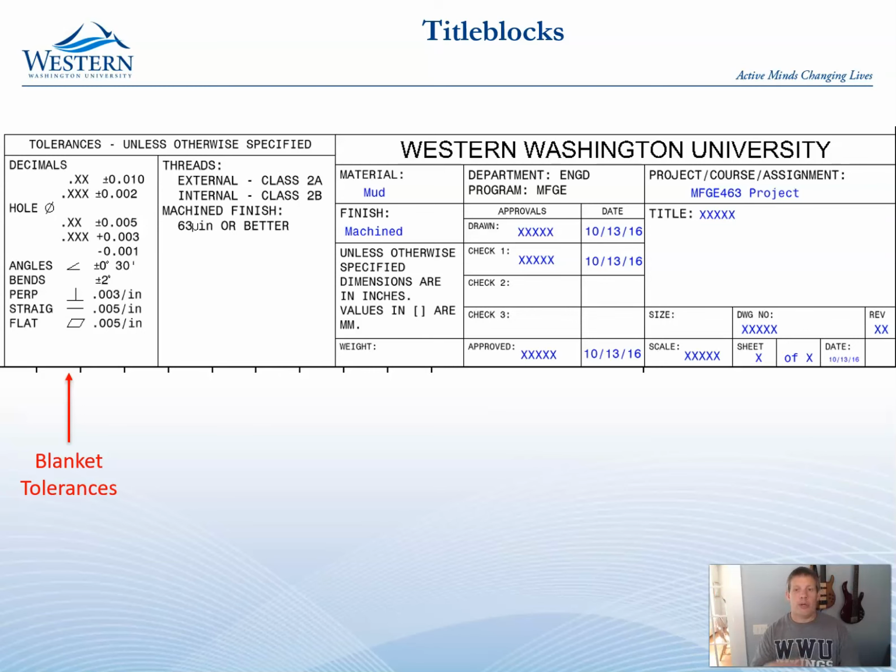But I don't ever want to see a drawing that has 4.3 inches and 2.1 inches, and then come down here to the table and see that there is not something that matches it. Also note that these are inch values, and you can tell that right over here in this box. It says dimensions are in inches. If they're in brackets, they're in millimeters.